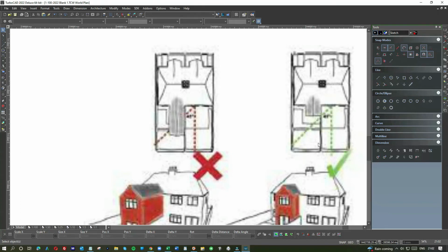This ground floor is fine, and the second floor, as you see, is coming out here. But there is a rule called the 45 degrees rule, which means that if you run a line at 45 degrees from the center of your neighbor's window, you should have a clear view. You do that line, it's not difficult to work out. If your extension comes beyond that, you're going to get an X in the box. You see this one? All the light that's being blocked into this neighbor's house. So that's an absolute no.